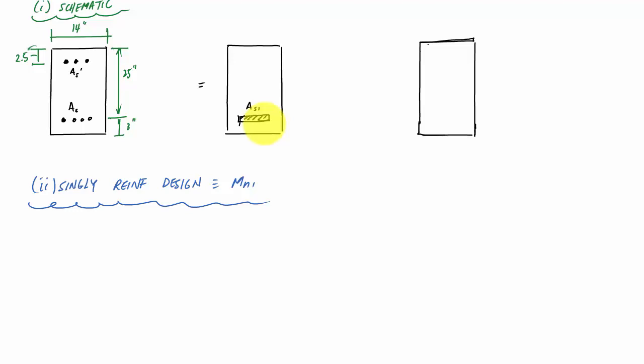That might take us into the transition zone for phi, which would be problematic. In the table in your textbook, for f'c of 4 ksi and grade 60 steel, rho at 0.005 is 0.0181.